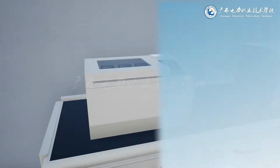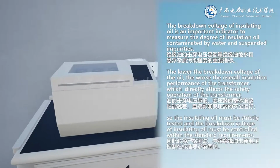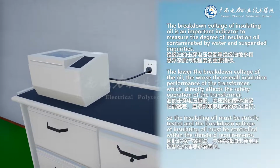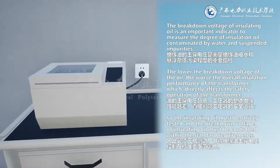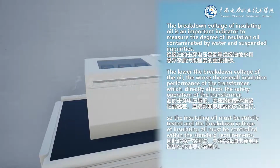The breakdown voltage of insulating oil is an important indicator to measure the degree of insulation oil contaminated by water and suspended impurities. The lower the breakdown voltage of the oil, the worse the overall insulation performance of the transformer, which directly affects the safe operation of the transformer, so the insulating oil must be strictly tested and the breakdown voltage of insulating oil must be controlled within the standard requirements.